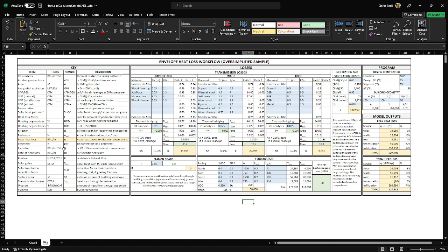This SIRF is a solar irradiation reduction factor. It takes into consideration, let's just look at it: a reduction factor that considers shading, dirt, and glazing fraction. In other words, if we have mullions in the window, that's going to cover some of the glazing, so we have to reduce things. If there's going to be dirt on the window and any kind of shading, we can put that into this.